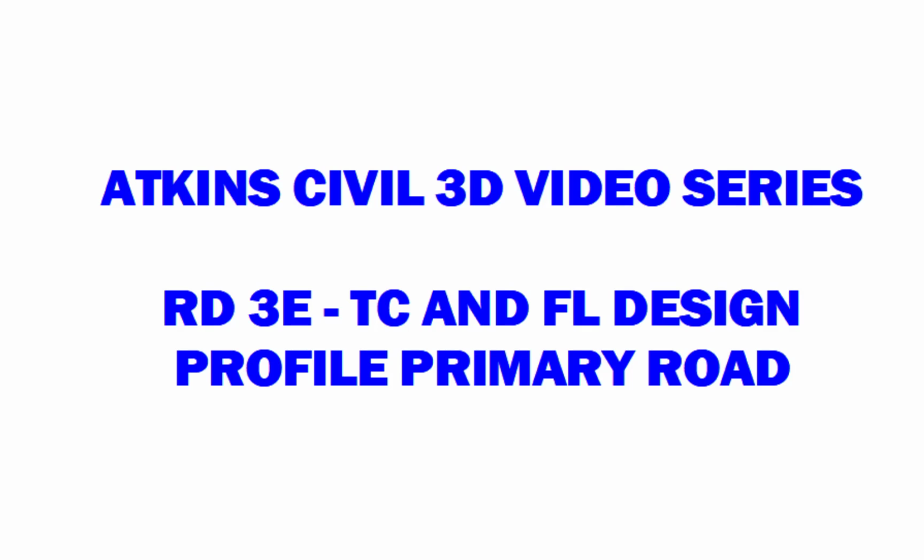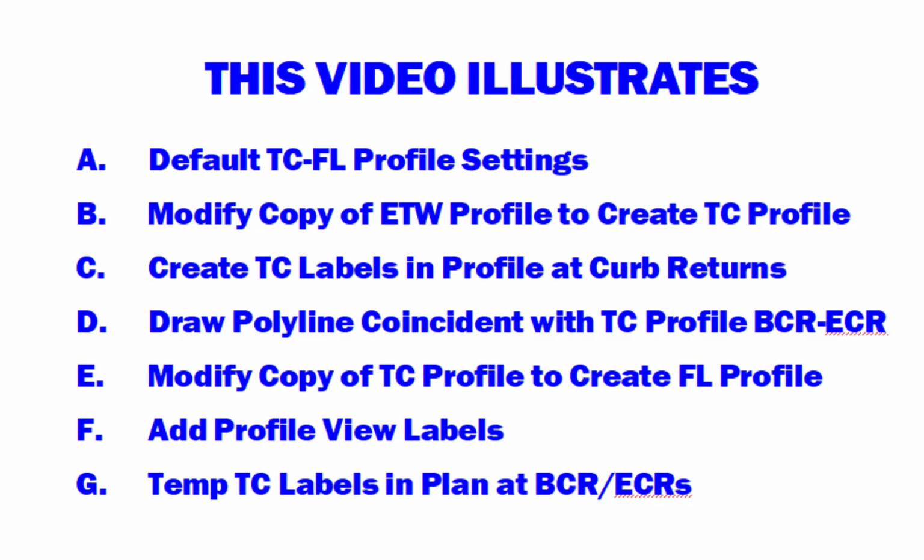Atkins Civil 3D video series, Road 3E, top of curb and flow line design profile, primary road. This video illustrates A. Default TC flow line profile settings. B. Modify copy of ETW profile to create the top of curb profile. C. Create top of curb labels and profile at curb returns.